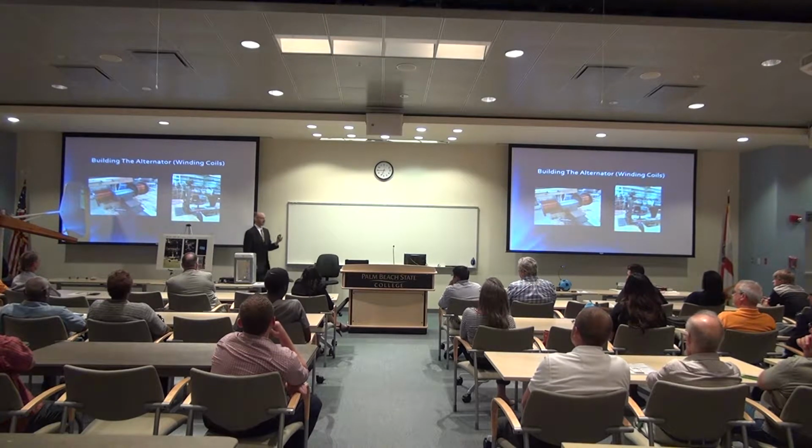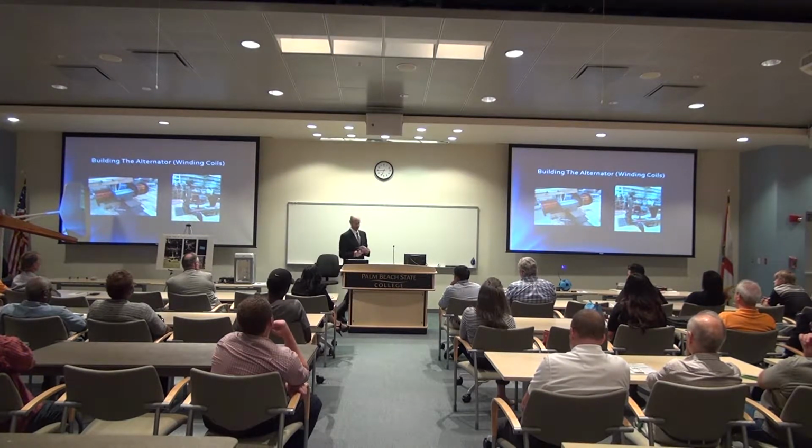This was a test coil. It didn't have nearly enough turns to produce the voltage that my generator needed. But they were hand wound from big spools of magnet wire. We had a little magnet winding jig here that was powered by a drill.